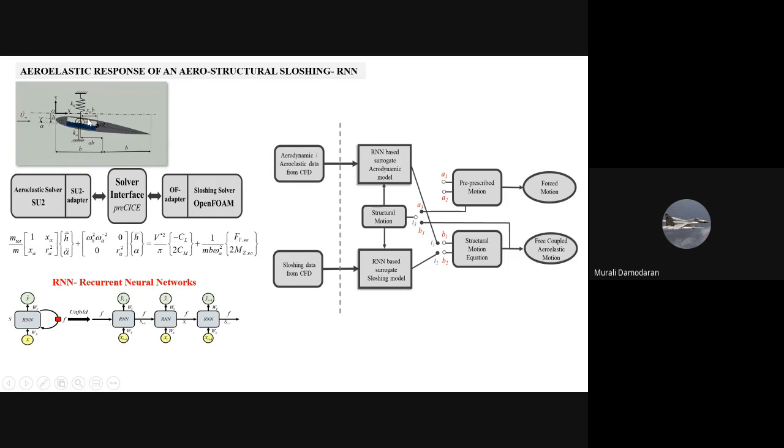And this is flying at a transonic speed. And this is pitching and plunging. So it's an unsteady external flow field. And inside, there is a fluid. The tank is half filled, so it will slosh inside. And when it sloshes, there will be forces on the inside walls of the tank. So how do we do this?